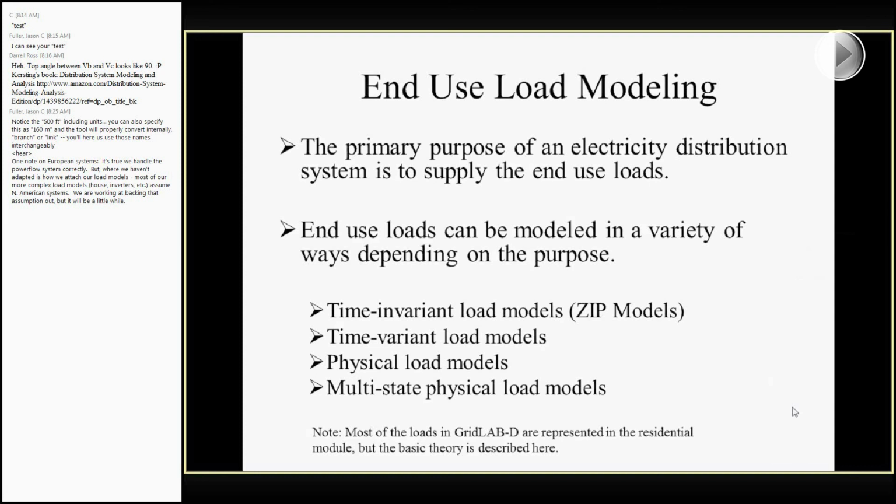So the other aspect of distribution system modeling that we've obviously missed so far is the end-use load modeling. We've had basically the links getting from point A to point B, but the big thing on a distribution system is what is the load on the system, and that's what's referred to as the end-use. The primary purpose is, of course, to supply power from your transmission system or your sub-transmission system down to your end-use loads. You've got to get power to your house so you can run your toaster, your TV, anything like that. And inside GridLAB-D, you can represent your objects in a variety of different manners.